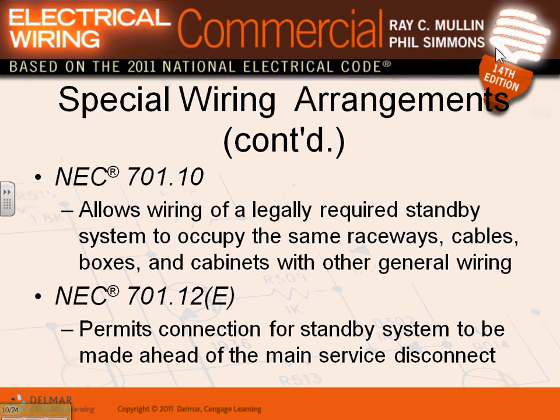Okay, that's basically it for emergency separation, and it needs 10 seconds. Now, wiring in the legally required standby system, Chris: if this fixture is a legally required standby fixture, I can bring the emergency circuit, the legally required standby circuit and the normal circuit in the same conduit. That's a major difference. They can occupy the same conduit in a legally required standby system.